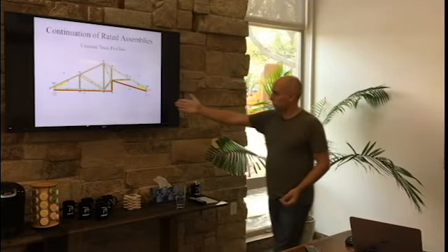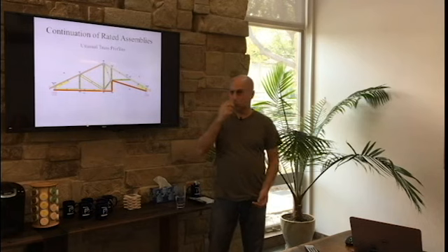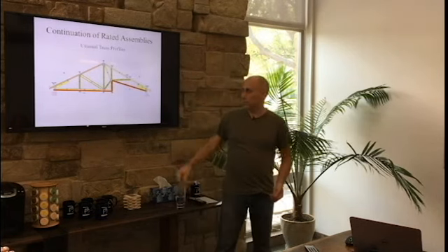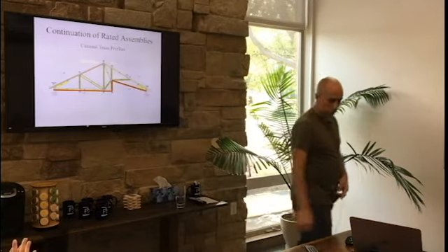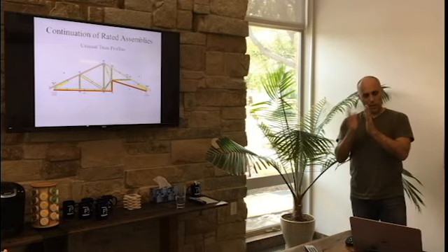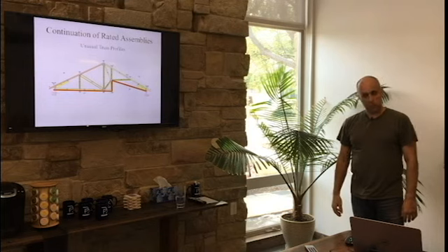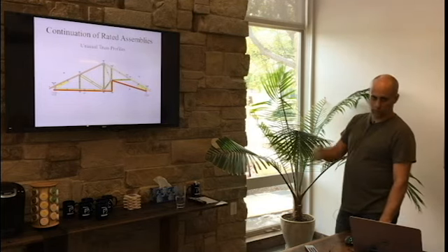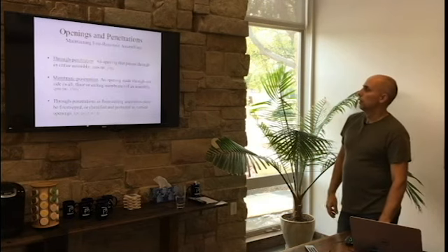So this face right here might have a bearing wall under it with 1 layer of type X, but this one here is either going to have 2 layers of type X to meet one assembly, or it's going to have the channels with that proprietary board. So it's not going to be the same thickness. So the truss has to pop back, or you're going to have something stick out. Just because they're in line with each other does not make them the same. They're different. A roof is different than a wall, it's different than a floor, it's different than a column.